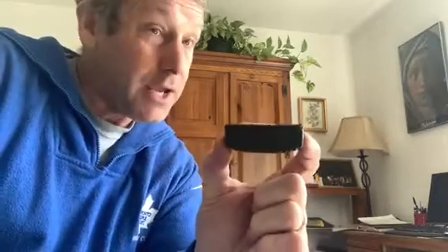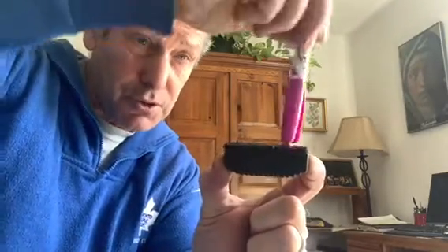Okay, well, the next thing I want to do with you guys is get going on the next option for collecting solar. So here are our options really quickly. Our first thing is just to build a box and make the top black, and fill it with water. All the calculations we did so far assume that the top of the box was horizontal, so the solar was coming in and hitting this surface here like that.